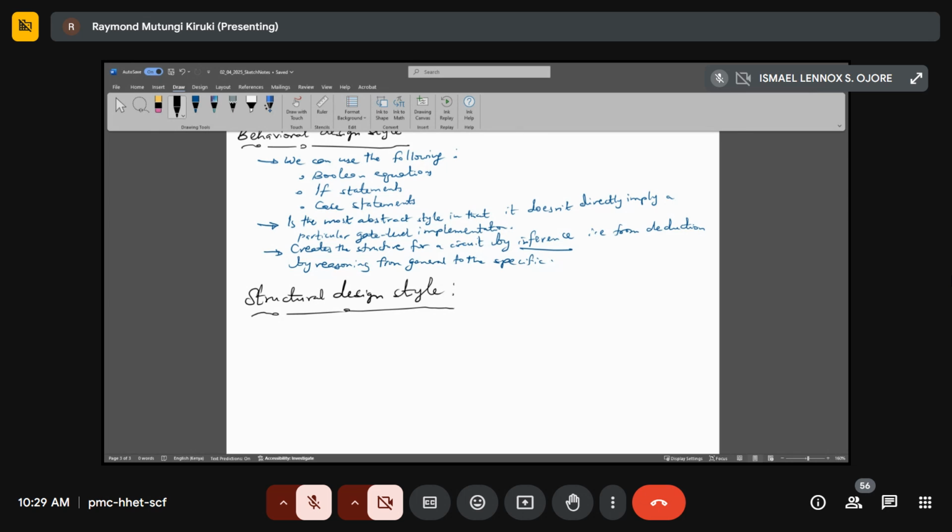And you have written code for that. So you have mapped the keypads, for the LCD you have the various commands and all that. You have programmed those in the respective .c files. And then in your main code, you will more or less be calling those particular functions that you have declared and defined in those other C files.